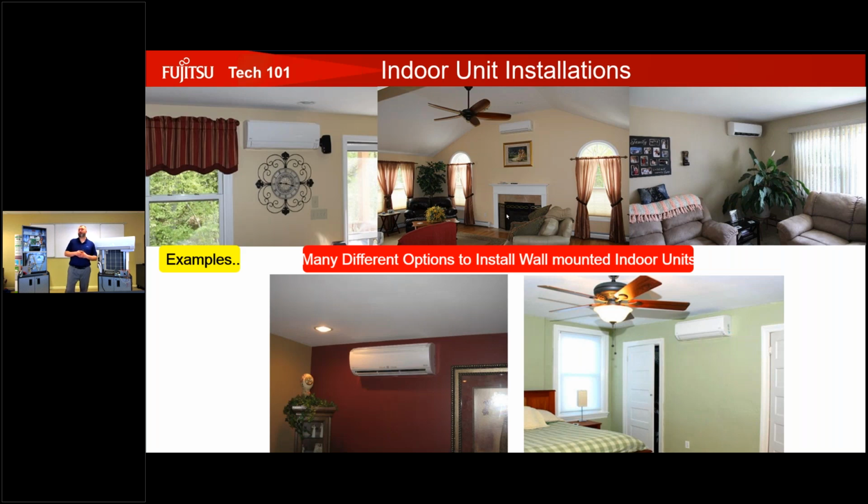Nothing really wrong with that bottom left-hand side. And on the bottom right-hand side, one thing that could affect this unit is, can't really tell depth because of the photo, but that fan could possibly deflect air back towards the indoor unit, causing a short cycling, which Jim had spoken about before. We might end up causing a cool and clammy type environment. So one of the things we want to make sure is that we don't have any possible air deflection points.